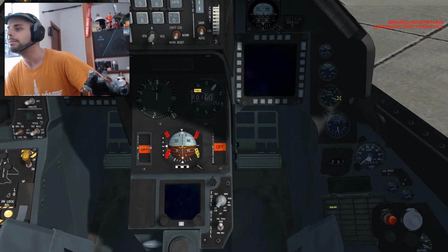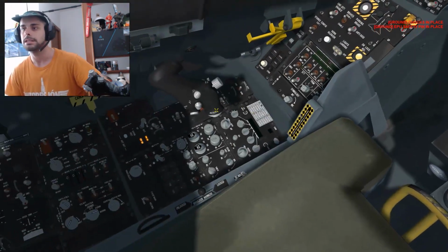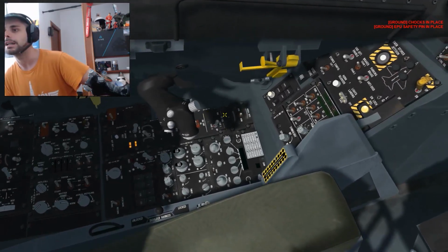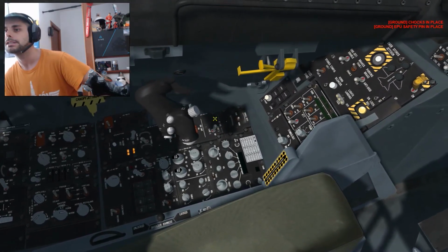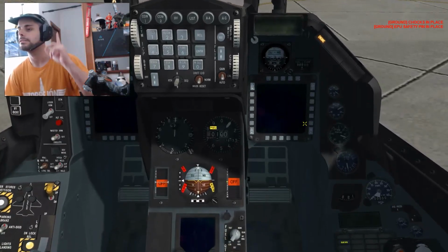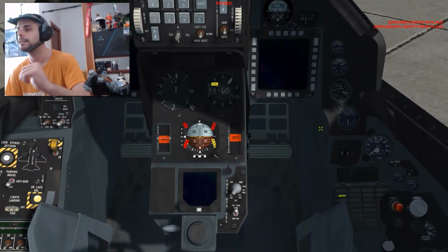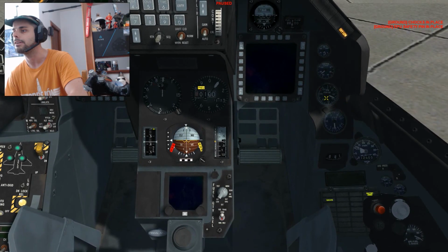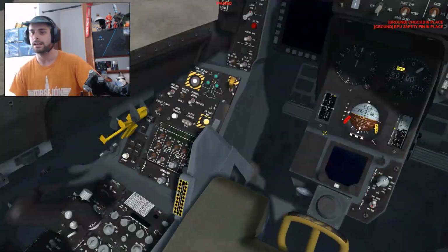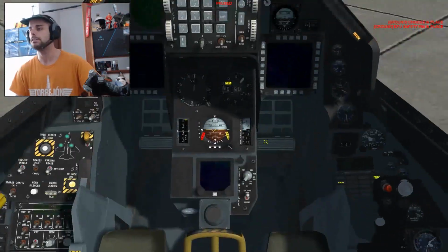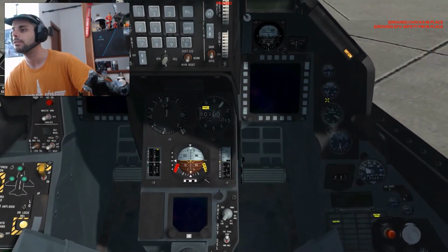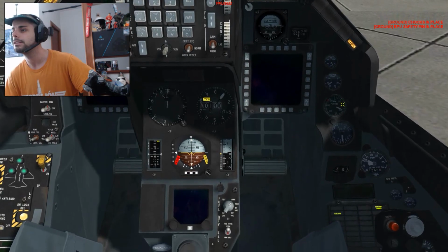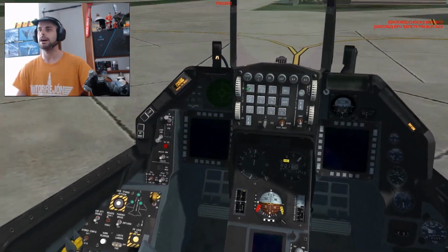When you are at 50% of RPMs, this light over here and also the jet fuel switch jump to off. Okay, and you also hear a sound. Okay, now around 60 I am getting energy from the generator. As you can see, I have oil pressure for the moment, and also a lot of systems now have light.